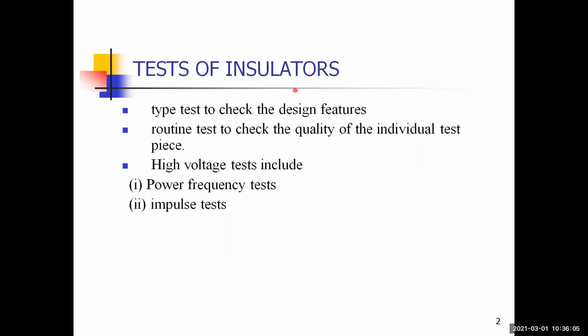So that is done in the laboratory. The type test is to check the design features. And the routine test is to check the quality of the individual test piece. So there are different types of type tests and routine tests. And the high voltage tests include the power frequency test and the impulse test.